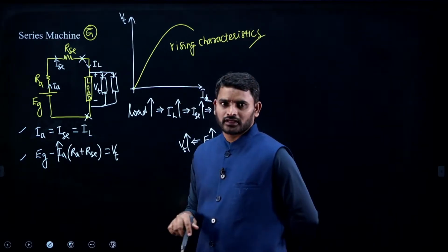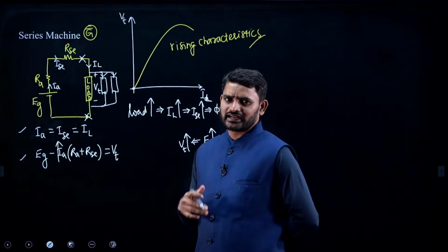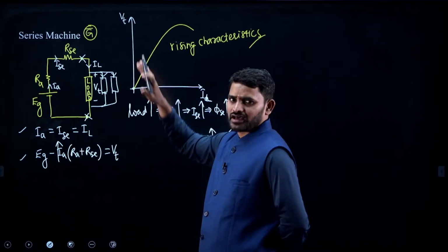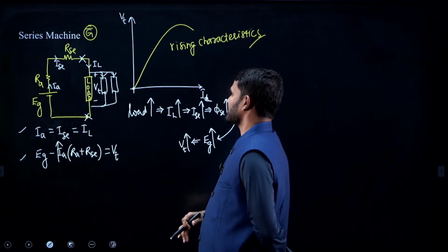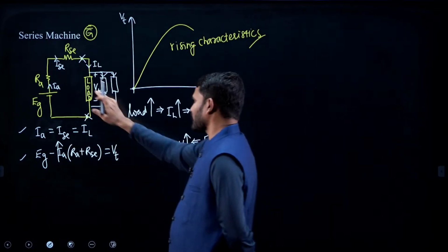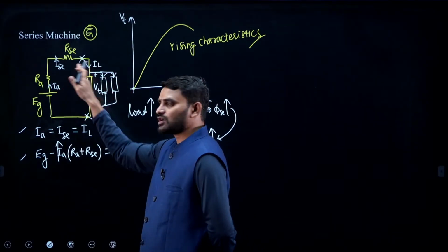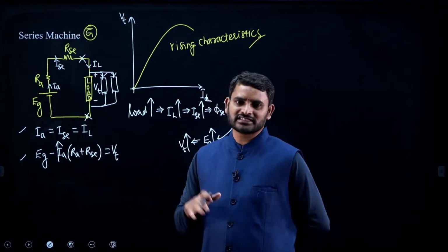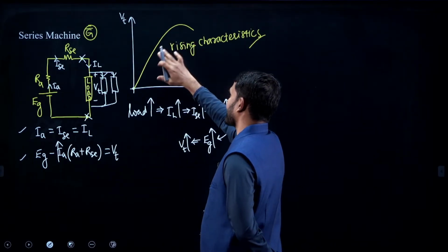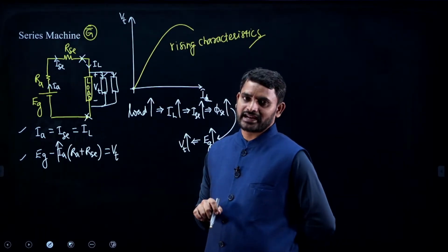Okay. Right. Coming to the no load and internal characteristics, we cannot draw them, it is just an imagination. We cannot draw them, because under no load there is no closed circuit, how can you expect anything? There is no current flow at all. Just an imagination. So, these are the external characteristics, which are generally rising characteristics.